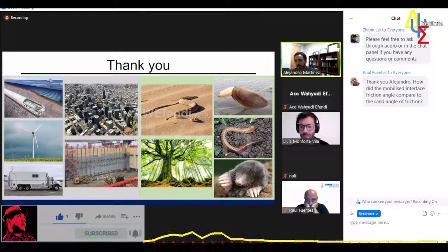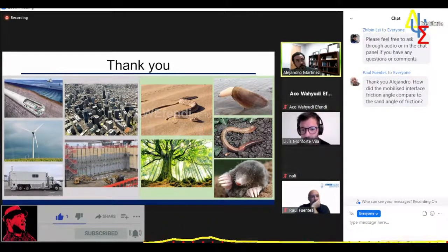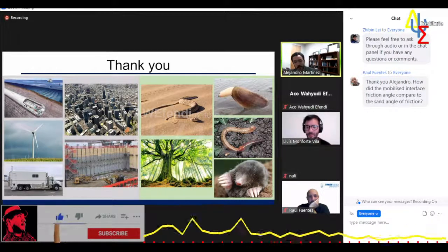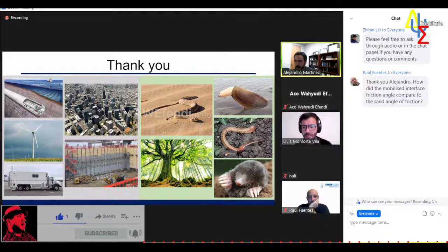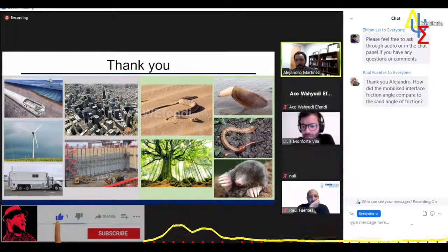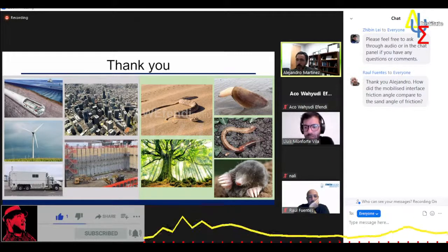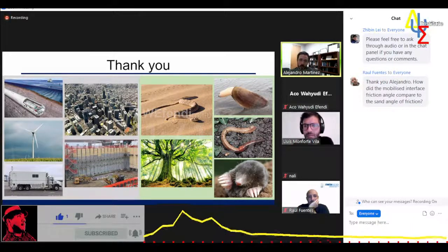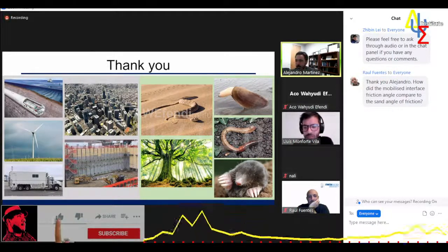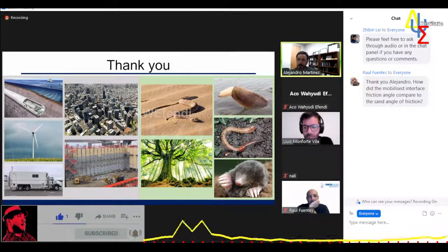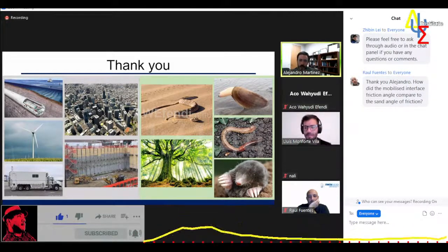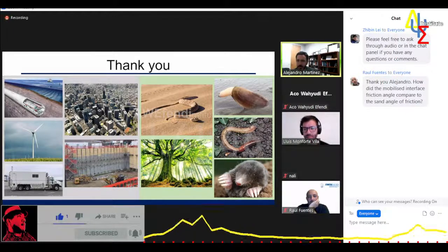In the laboratory, for the surfaces with the tallest asperity, they were pretty close to the internal friction angle of the sand. In the centrifuge and in the field, we can't really compare because we don't know the magnitude of the effective stresses. But at least in laboratory, we see that kind of an upper bound appears to be the internal friction angle of the sand.